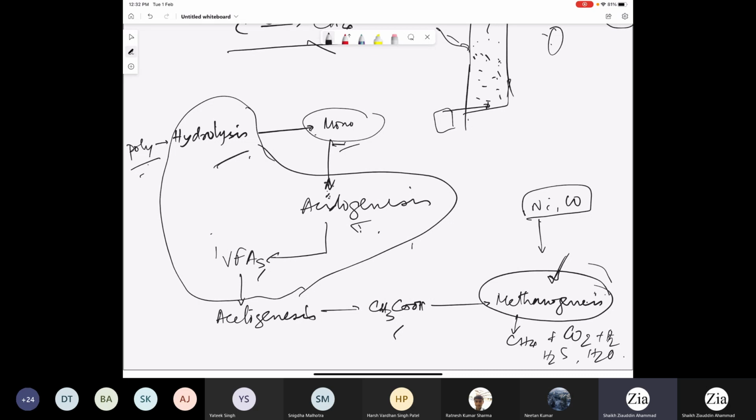So we always try to optimize the reactor by maintaining healthy conditions for the methanogens. Now, in some exceptional cases, you can still get the first reaction as the rate limiting step. In cold countries, like when DRDO tried to install their anaerobic digester in Siachen this year, or at high altitude, they realized that wherever you get a really prolonged winter, hydrolysis could be the rate limiting step, because hydrolysis is essentially just the breaking down of polymer to monomer.